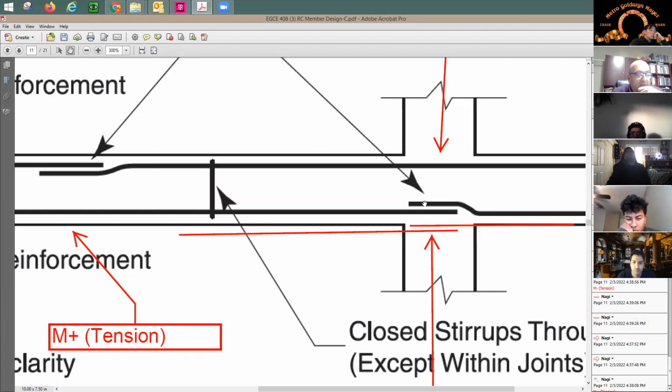Or also you can do it this way, but that means you're going to be bending the bar this way, right? We call this a splice. So the two rebars are going to be next to each other, like this. We call this lap splice. What does it mean by lap? Lap is this length over which we are putting the rebars together. A splice because you're splicing the bar. You have one rebar here that is going to stop. This rebar is going to be the continuation of it.